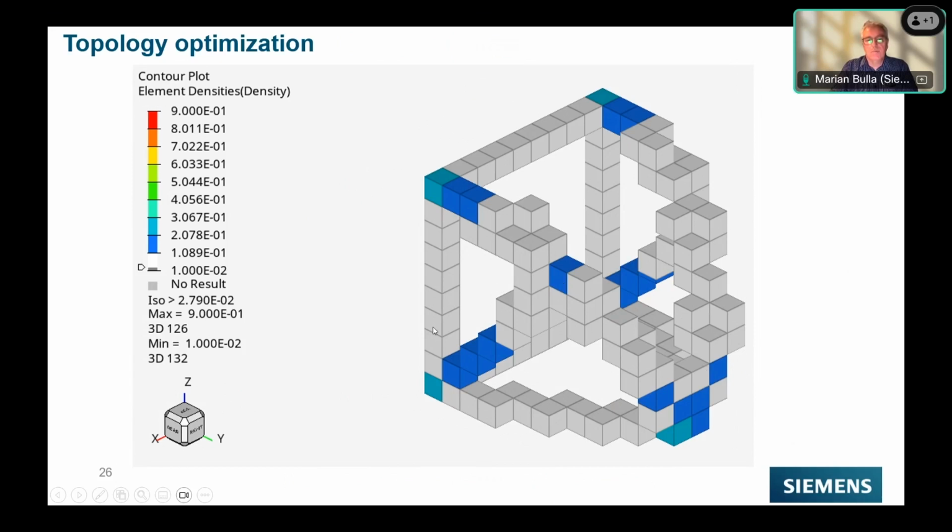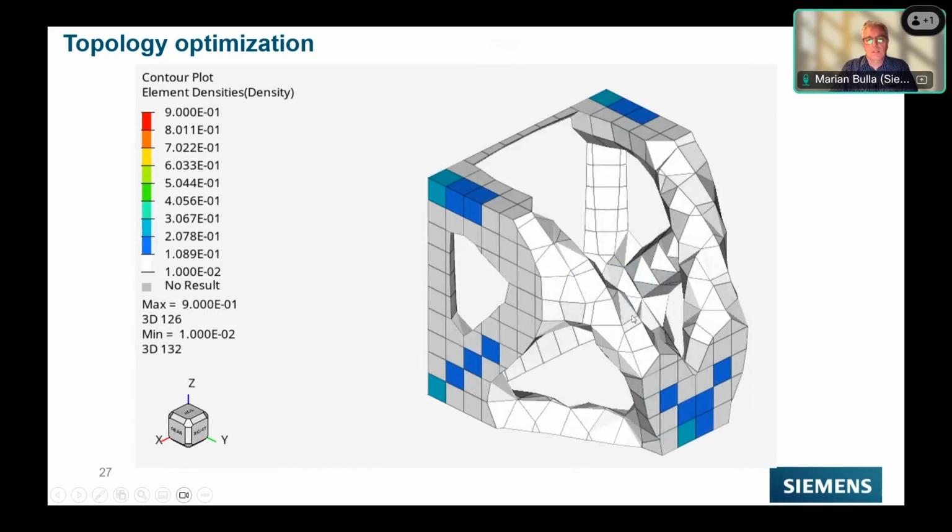You can for sure smooth it, and if you smooth these results, it will look like this. Anyway, not very nice, because I wanted this coarse mesh since it runs very fast in the optimization. This is the remaining structure after the OptiStruct optimization. So, smoothed results with the coarse mesh, still not very nice, but much better already.